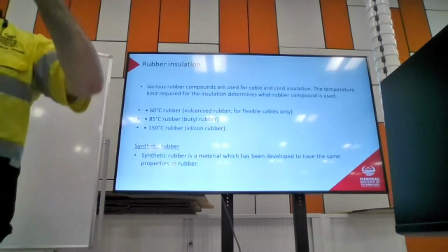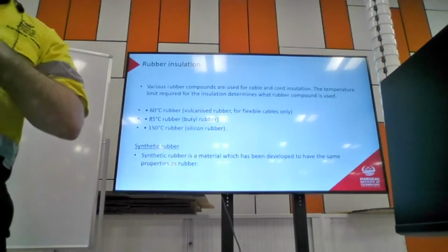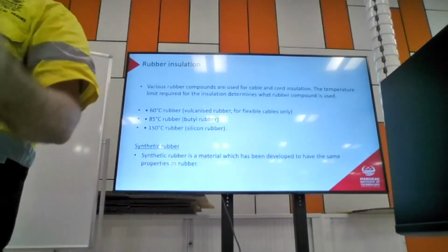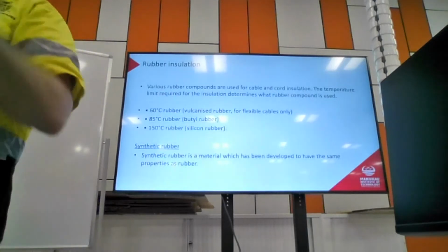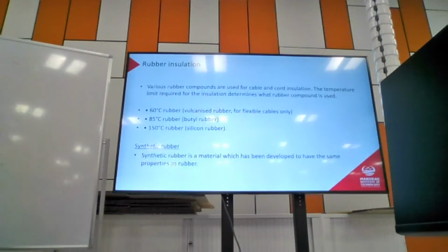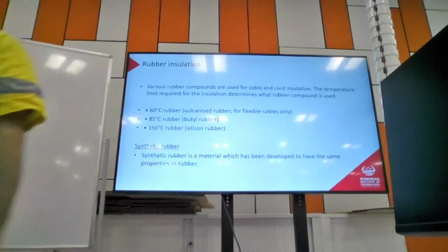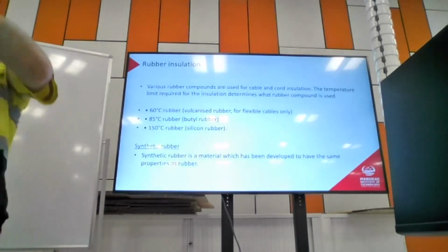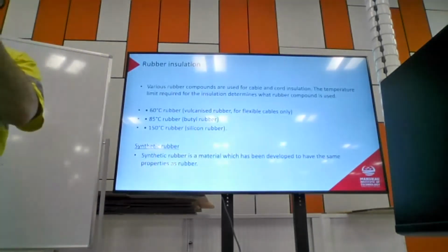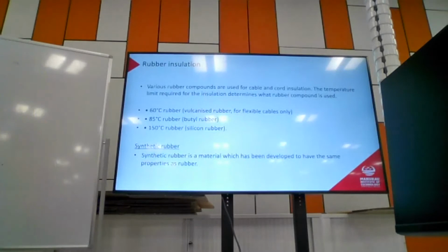Even something like taking a socket off, and as you pull it out from the wall, all the insulation from around the cores will crumble away, or can crumble away, which means I've got to replace that cable. And I've had situations where maybe I could just re-sleeve it, but then the more you touch it and move it, the more it starts to fall apart, and you just make it worse and worse until you give up.